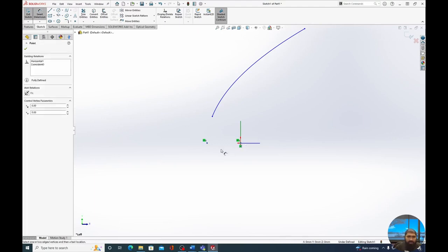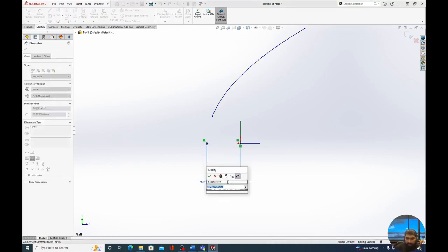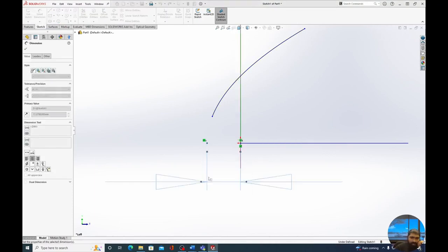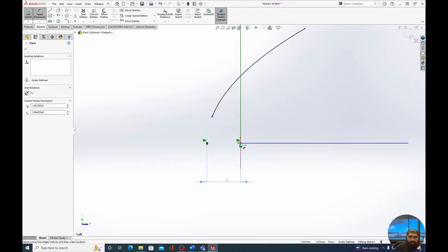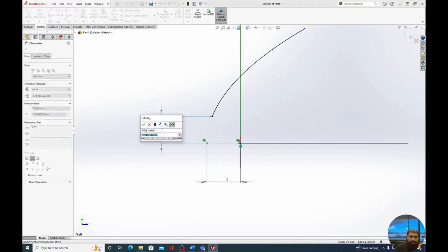The first distance we're going to put is to the bottom of the parabola all the way to the focal point. I call this the bottom because if you've learned parabolas, you usually deal with them upwards like this. So I'm going to set this distance to 2 millimeters and press OK. The next parabola distance I'm going to have is between here and the bottom. So top to bottom, this will be 4.